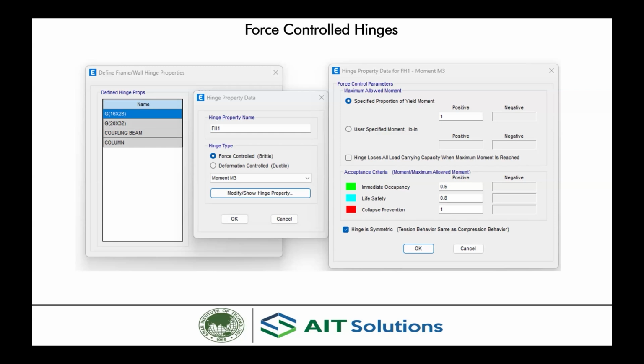The program will calculate the capacity from that reinforcement for that section, and give you back demand to capacity ratios for that action from time history analysis. So say, for example, you might want to check beam shear. If you have provided beam shear reinforcement in the section, then the program will calculate the beam shear capacity from the section and then use that capacity to give you the DC ratio.